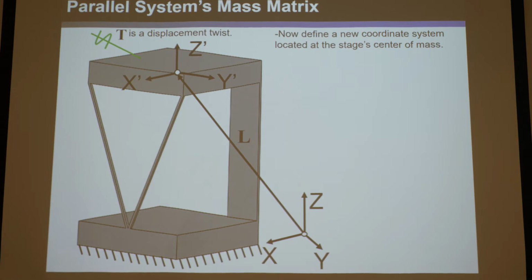But if you locate them along the principal directions, okay, which are usually easy to intuit and find, and for a rectangular prism is just obviously the directions that are perpendicular to all the flat faces, then they will be the principal directions, and the inertia tensor goes to just a diagonal matrix. So it's all 0 everywhere except the middle, the diagonal 3 will be non-zero. Okay, and those are the ones we can easily calculate.